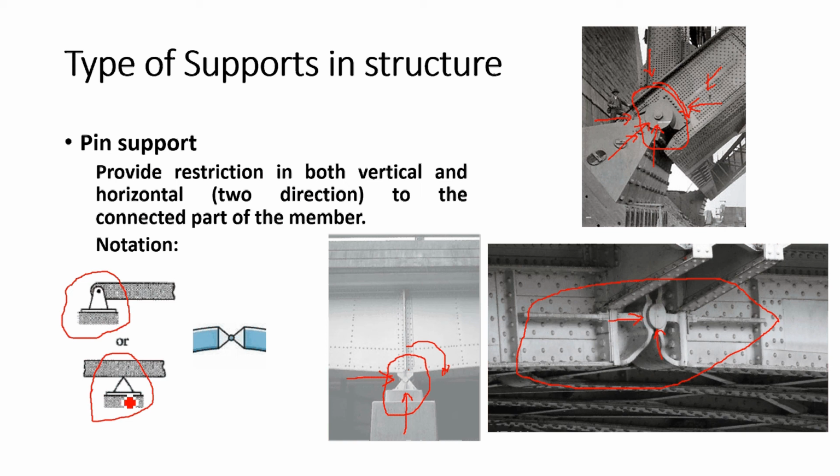When you talk about these internal hinges, this is the notation we are using. You can see the internal hinges also here. When you try to rotate the members, it will allow your member to rotate about both points, right? You can observe that here in these notations. It will allow your rotation about these two points. It will not provide any restriction against the rotation.